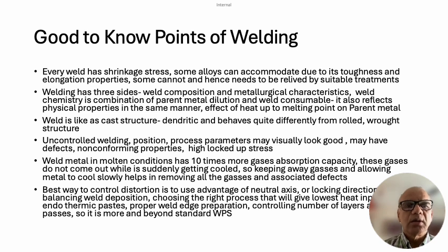The second is the parent metal itself, which is undergoing different heat treatments, because the different cross sections from the weld towards away from the weld will undergo different thermal cycles. Some of the cycles will be hardening cycles, some will be stress relieving cycles, some will be half annealing cycles, some will be normalizing cycles. So each of the cycles on that parent metal is going to be different.